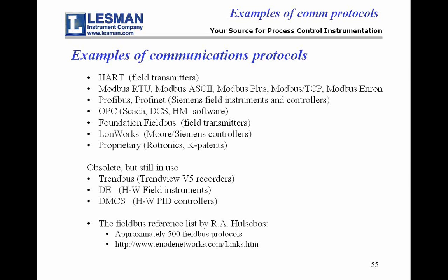These are examples of communications protocols that we run into in the industrial world. Everybody's probably heard of HART. That's used widely for configuration of data. It can be used to transfer data, but there's a fairly small niche for that. You'll see that there's all sorts of flavors of Modbus up there, none of which, by the way, are really compatible with one another. And you'll see on another slide that we have protocol converters that can actually convert from one protocol to another.